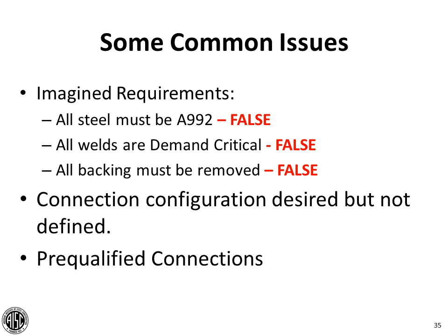Yeah, so just very briefly, a demand critical weld, there's a couple ways to look at it. So the reason we have demand critical welds is discussed in the commentary, I think to chapter D, I believe, and it talks about the inelastic demand, the high stresses and inelastic demand on these connections. So that's kind of why they're required. When are they required? They're required when listed in the specification or by the engineer of record.